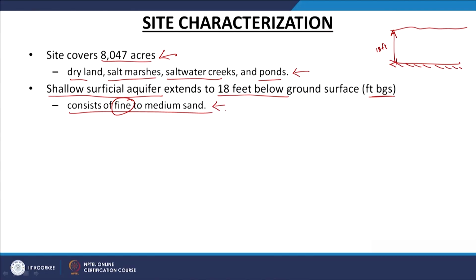That is something to keep in mind. One, permeability is typically high for sand layers, and also because of the typically lower organic fraction of carbon, the contaminant would not have been adsorbed onto sand, but would have transported through it, or most of it anyway, right.